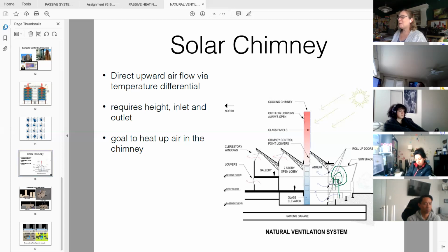I got distracted though. The other thing I was going to mention is that in working with the physics professor from UCSD, they did an analysis looking at different types of glazing on the building and how much it was going to heat up or cool down. If you recall, when I said if you're doing a passive solar system or Trombe wall, you don't want to use low-E glass, because you want that heat gain to come in at the time of year where you want it, and you want it to hit that thermal mass and store that energy.